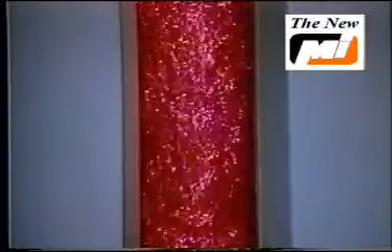A close-up of this zag tube clearly shows the slower hindered settling typical of vertical intervals. In this environment, as cuttings begin to move downwards, they run into other cuttings. They also displace fluid as they move downwards, which creates an upward flow that further slows the cutting. In this clip, some cuttings are actually moving up the hole, others seem stationary, and still others are moving downward with the pull of gravity.